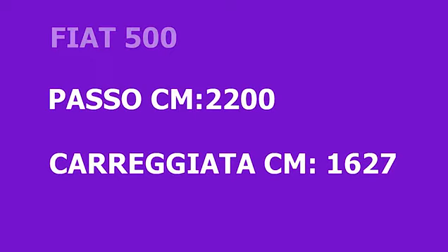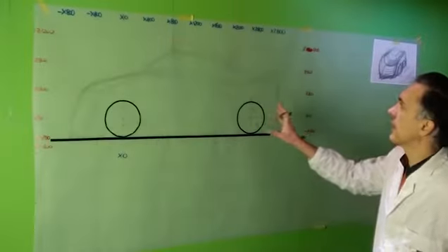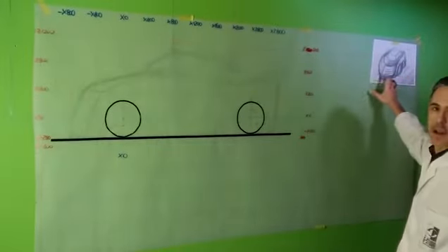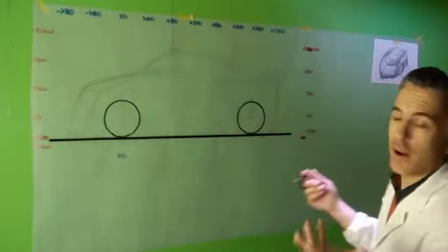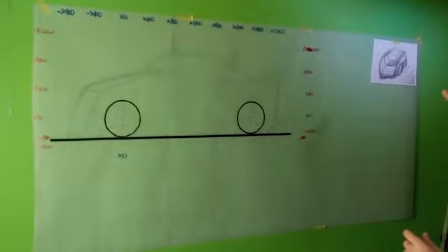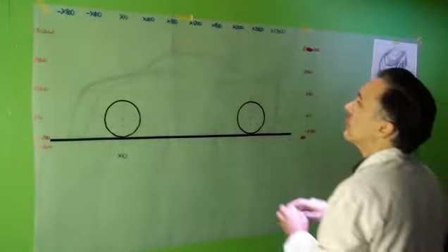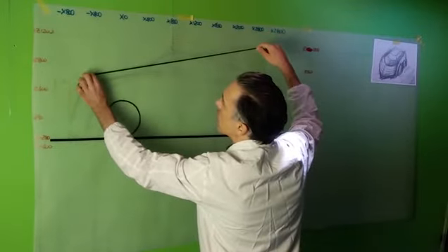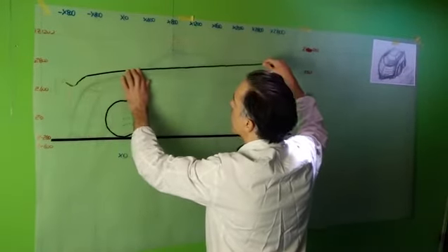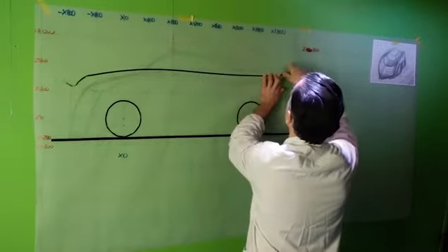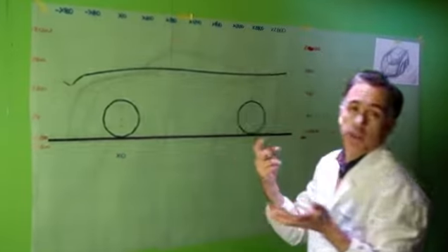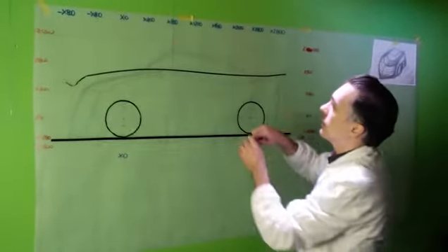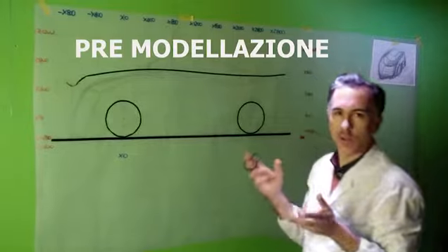So now, without further details, I have to start redefining and transforming my sketch into real dimensions. So, how do you do it? By eye. You look at it. I look at my sketch and start drawing it with the tape, starting from the main lines. Tape drawing allows you to do 2D pre-modeling, so I am already modeling the car.